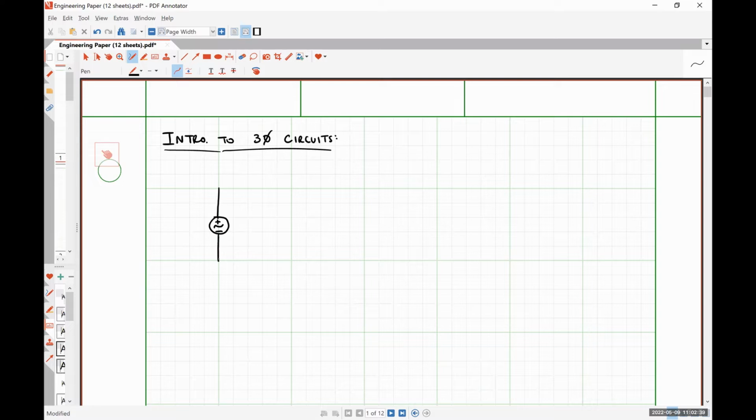We have a sinusoidal source that we can represent using the following voltage, where VP in this case is going to represent what I'm going to call a phase voltage, and it will be an RMS quantity. Okay. 99.9% of all of the voltages that we're going to reference for the remainder of the class will be considered RMS voltages.